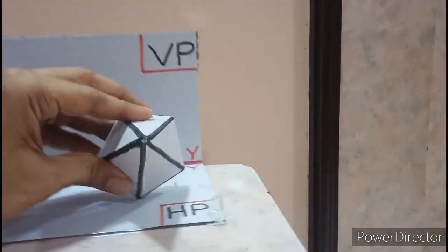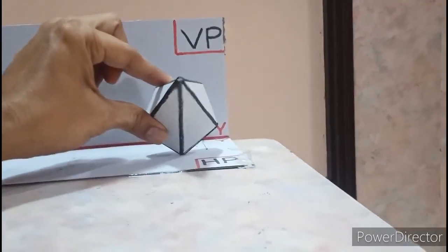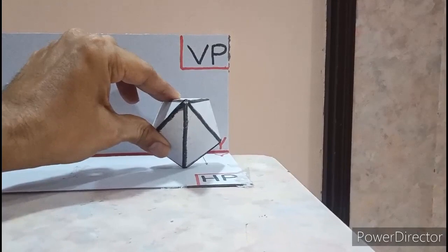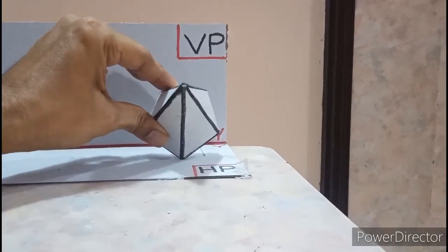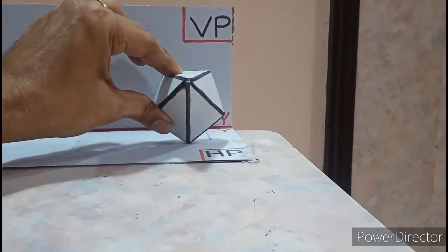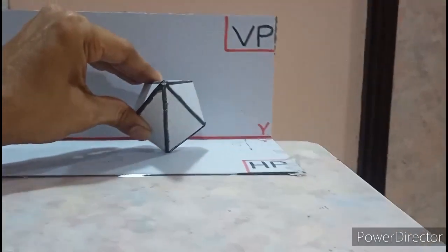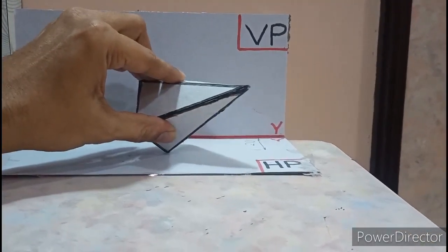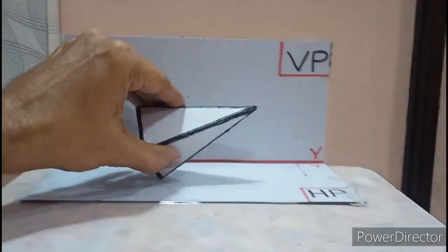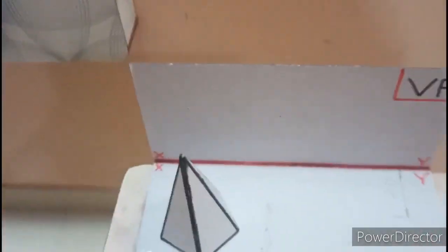So this is our last stage, front view and top view. If you look at this last stage front view, the top triangle is perpendicular with VP. The topmost triangle, which is seen as a line, is perpendicular with VP as well as parallel to HP. So this is the third stage. In the second stage, we will tilt this by 90 degrees and make the axis parallel to VP from the top view. And in the first stage, we'll make the entire base rest on HP such that the corner should be on the right side.